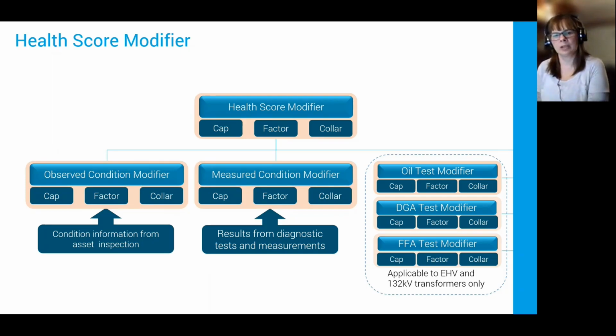But then if you go and do a residual strength test and you see the cross section of that asset and you realise that it's got good strength, then that would potentially override the poor observed conditions. So you might set a cap and say, actually, it doesn't look great, but we've tested it, so we know it's intact and it's fit for purpose. And so that's when we'd use a cap.